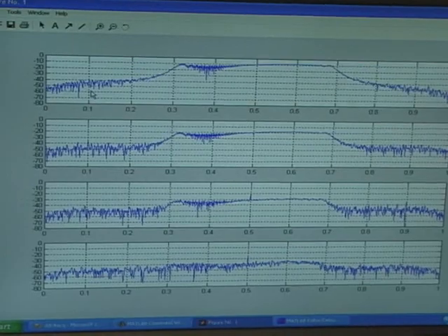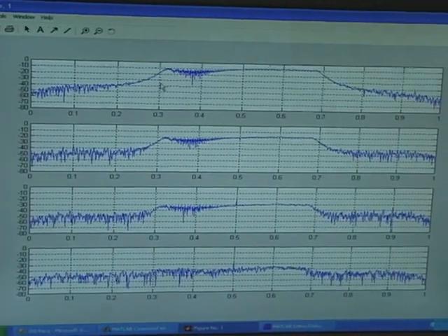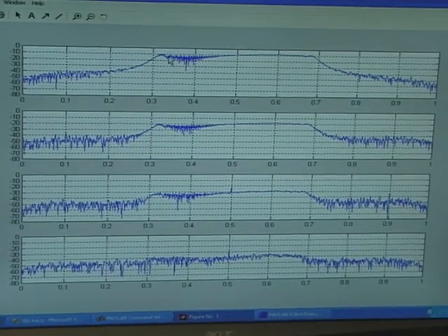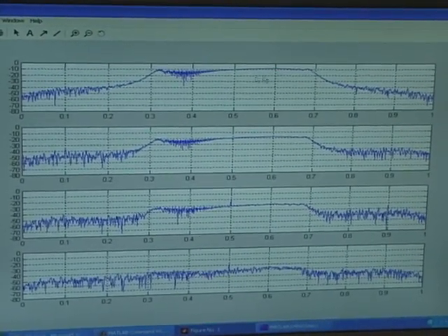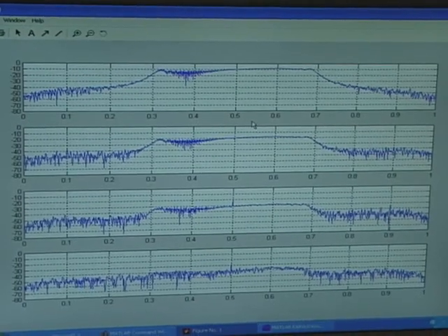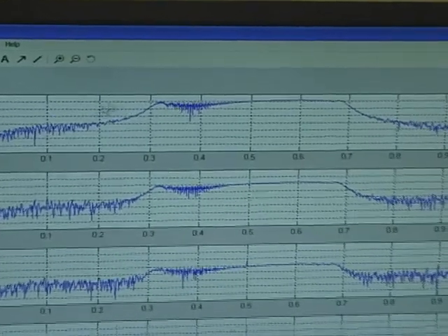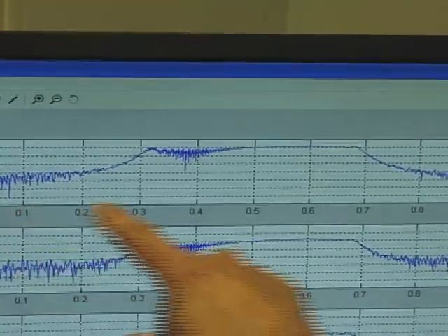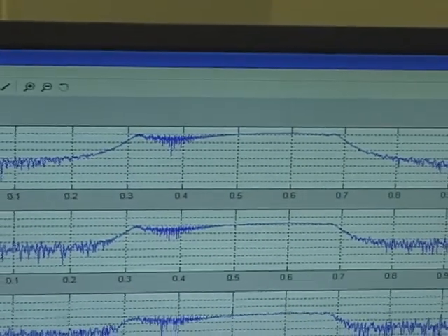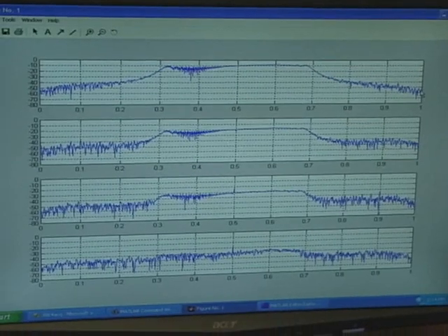And you can see that the entire range of the signal shows you about 4 boxes here. We know that the top of this is about 5 megahertz. 4 boxes out of 10 would therefore correspond to 5 divided by 0.4, giving you 12.5 megahertz complex sample from here to here. And that's, of course, the bandwidth of the digital filter in the DDC.